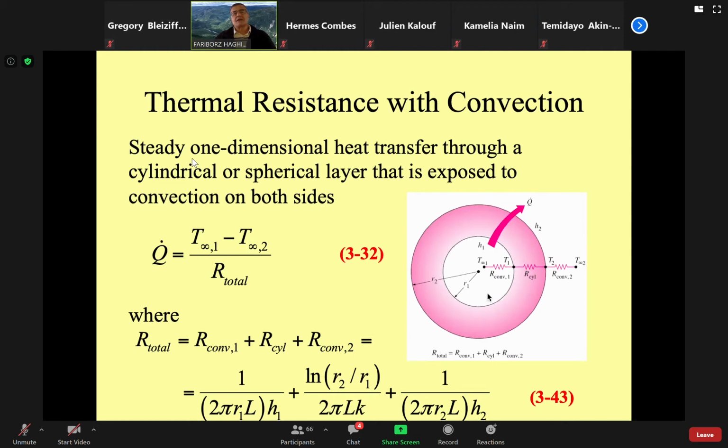And for the inside, I'm dealing with these surfaces here, okay? This is the scenario we are dealing with. Now come back to the solid here: the heat transfer resistance, as we defined, is the ratio of these two radii, ln(r2/r1), divided by 2 pi L k. Any question, please?